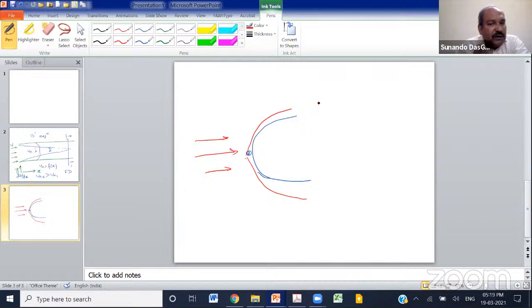So inside the boundary layer, as we move in this direction on a curved surface, the flow area becomes smaller and smaller because of the curved nature of the surface, and the adverse pressure acting on the moving fluid keeps on increasing.